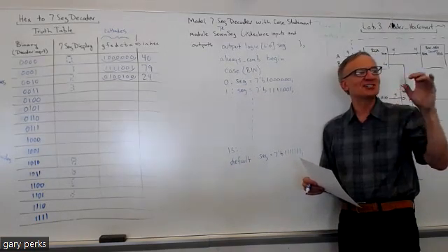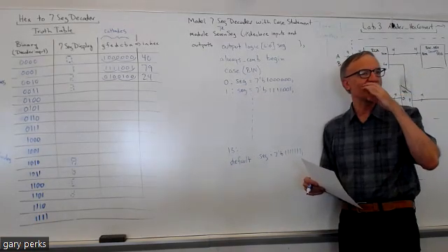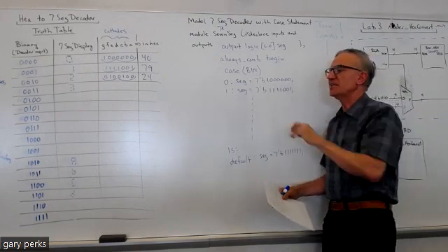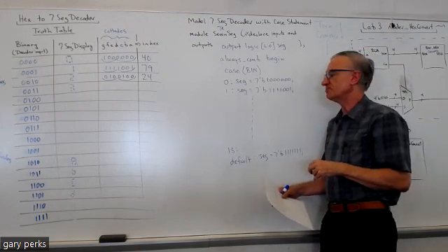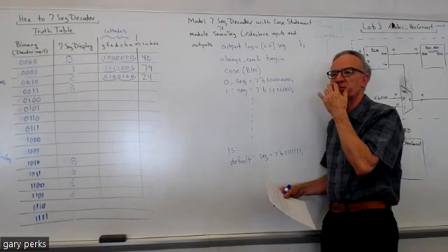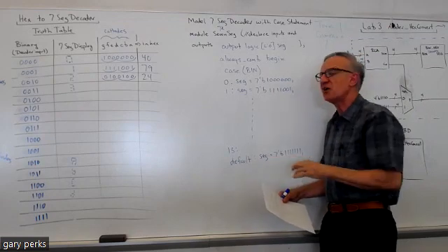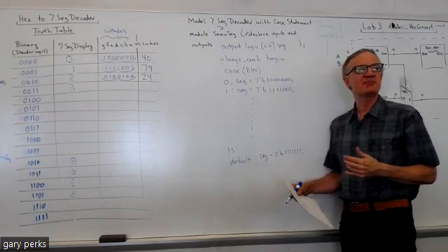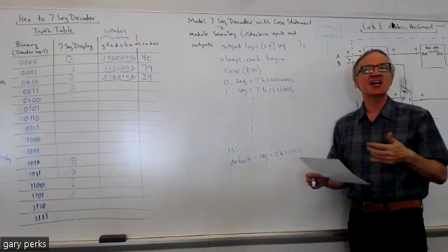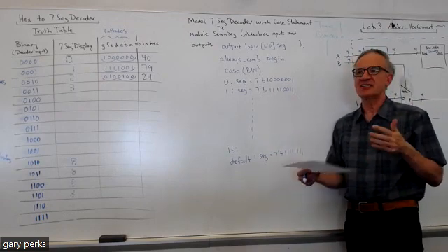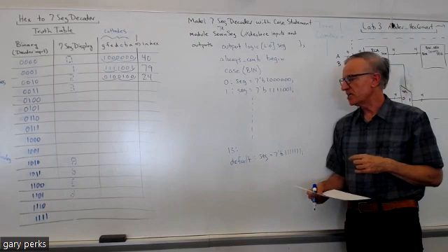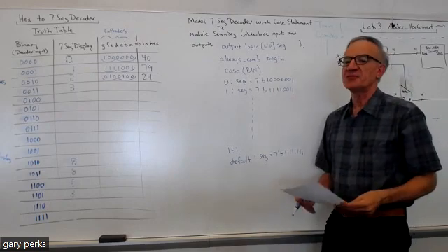Like one bit might change a nanosecond before another one, but it might be enough where it causes an ambiguous situation. And having the default will keep it from getting hung up, like an infinite loop or something like that. So you always want to have a default.